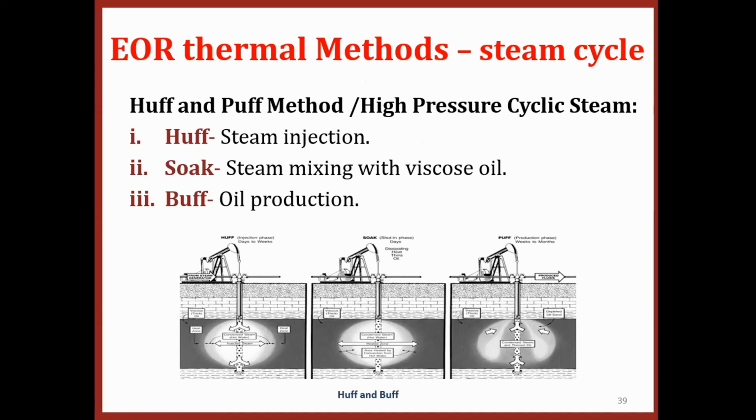Then I leave the steam inside the well, captured there, for maybe 4 or 5 days. We call it soaking time. Then after the soaking time, I open the choke at the wellhead and the oil will come produce. I produce for a full month. So I do lose maybe 10 days, but I produce for 30 days, huff and puff.